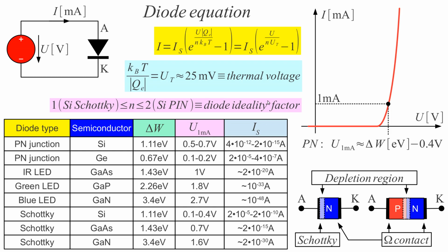so the way minority carriers are getting recombined in a rectifier. This ratio here, charge of an electron divided by Boltzmann constant divided by temperature, this ratio has the units of volts, and in fact at room temperature it's around 25 millivolts. So we are going to call this thermal voltage to simplify our equations, not to carry around so many physical constants here. This is for the ideal diode without other effect, just the diode effect.